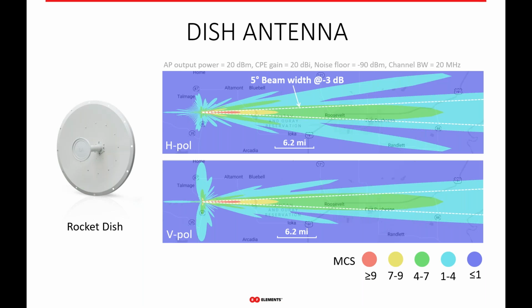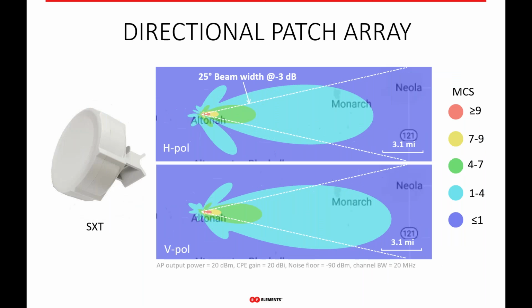So again, just to reiterate, dish antennas are mostly misunderstood because everybody fixates on that 5-degree, 4-degree, 8-degree main beam width. But when you look at all the side lobes and where the radiation really goes from that antenna, it's typically much, much wider than you think, right? So, looking at the real coverage plot, more can be said about the antenna.